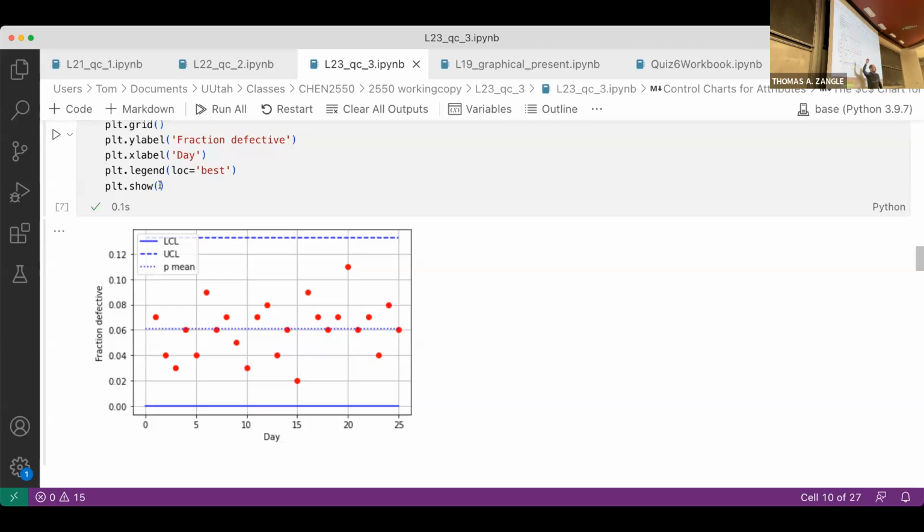There we use the acceptable limit to construct that hypothesis test. Here, we're not interested in whether or not the result is acceptable. We're just interested in whether or not the result of our process is stable. So we construct our limits based on what the process looks like historically, and we're just looking to see if we're veering inside or outside of those limits. So there's a bit of a distinction with what we've done in the past.